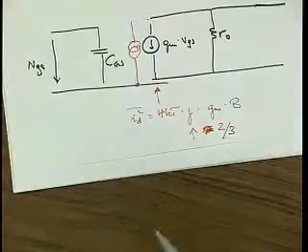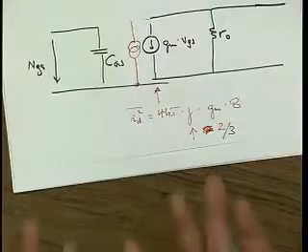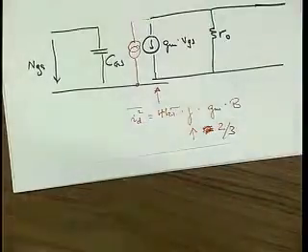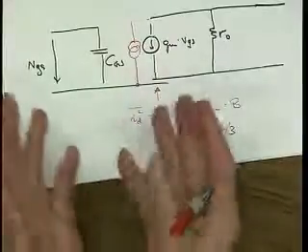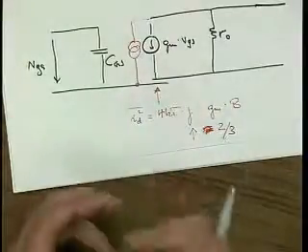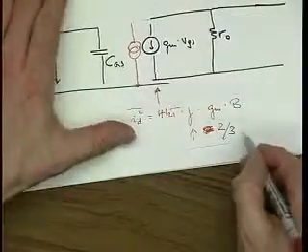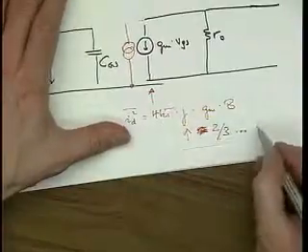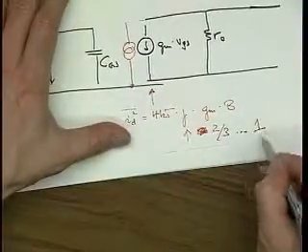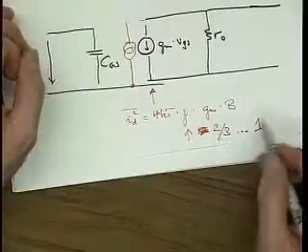If you use a MOSFET to synthesize a resistor, then you apparently get only 2/3 as much noise as you would get from a normal two-legged passive resistor, but then you would have to stick in power to make it a resistor, and it would be nonlinear. Sometimes in practice you find that this gamma factor is a little bit larger, and because I just hate to write 2/3 all the time, I often make it 1.